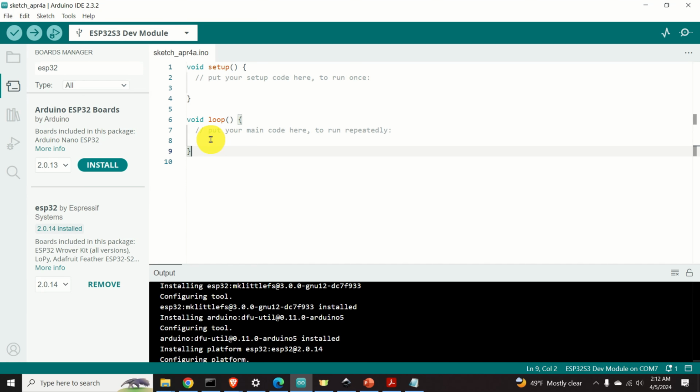Now that we understand the basics of communication and what is the purpose of the client and what is the purpose of the server, let us explain the script implementing the Wi-Fi server. The first step is to attach your board to the computer and, of course, to build a simple LED resistor circuit. Under the assumption that you did that, and to briefly summarize, the LED should be connected to the pin number 5, and the other side should be grounded. The purpose of the resistor is to limit the current through the LED. Otherwise, the LED will explode.